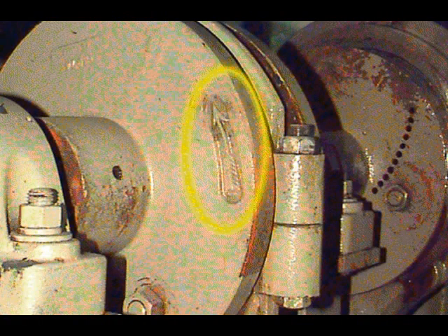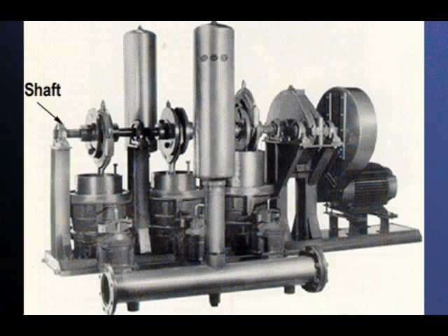First, the direction of rotation of the pump should be checked to be sure that it conforms with the directional arrow on the driving flange. Notice the arrow on the flange in the picture. Before checking the rotation using the motor, it is a good idea, once the unit has been locked out, to turn the pump shaft at least 1 revolution by hand to make sure that the pump is free of obstructions.